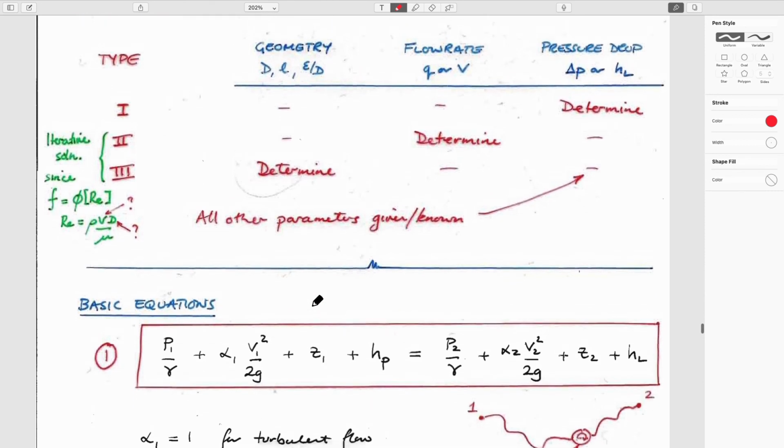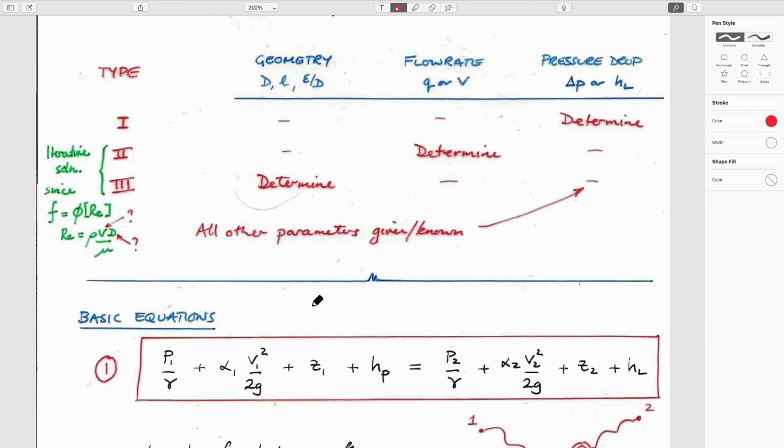And so I won't write Bernoulli for you, but you see it there. I snuck it in. But we'll make a case that if we want to solve for real problems, we have to do something, and we can rationalize these different types of flow that we solve for. And last time we took care of this type 1 problem. And so all they do is they differ on what we know, what parameters we know. For the ones that we solved before, we knew the velocity, and we knew the geometry of our piping system, and we wanted to know what the head loss was.